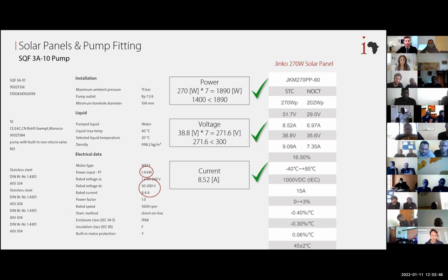Why? Let's say I'm using a pump and I have the controller. We also need to be aware of the controller limit of current. And I'm going to touch on it in the next slide, because the controller may have a limit of 10 amperes, which is true for the CU200, let's say. And it has a fuse inside, which will burn the moment it exceeds the 10 amperes. So the electrical engineer needs to be aware also of the controller limits, so we won't burn out the controller.